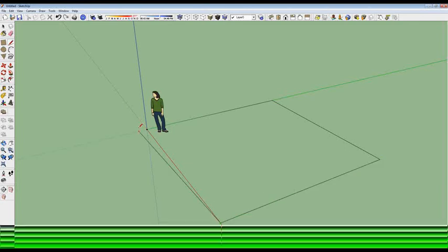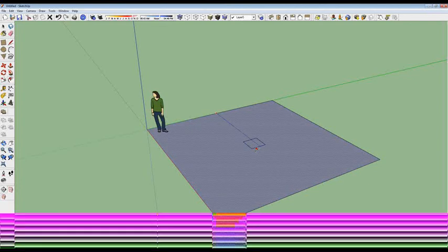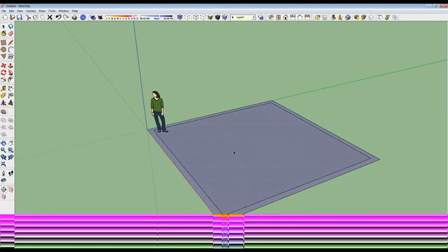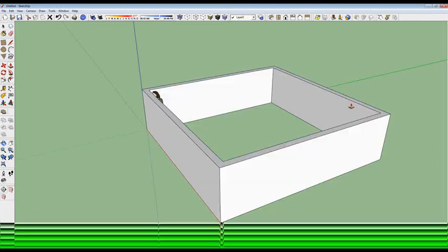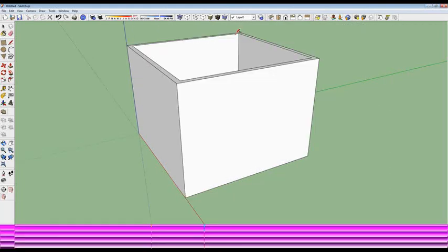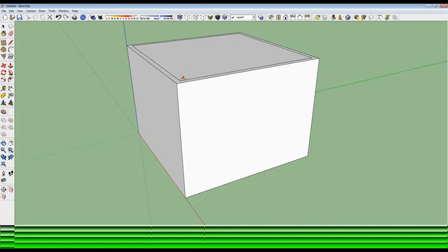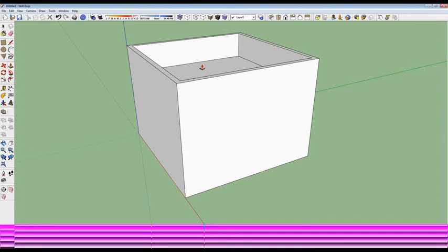So I can move around and find that axis, close that in, get a surface. It's just a face that I can push and pull. Take and offset it. Maybe I want an 8-inch wall. Delete out that middle piece, and I can pull this up for a 15-foot building. Nice, encompassing Susan there. Same situation for the parapet wall, so I want a flat roof in here. I'm going to close in that surface and drop this down 4 feet. I just clicked and dragged down, and it knows to go in a negative direction as well.